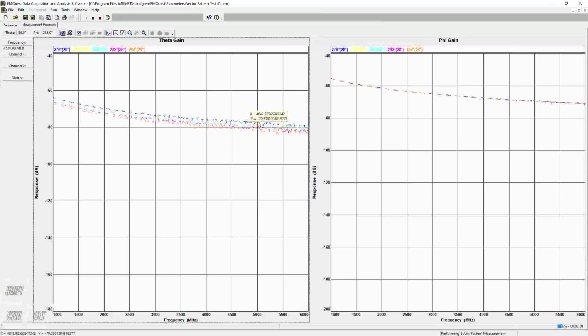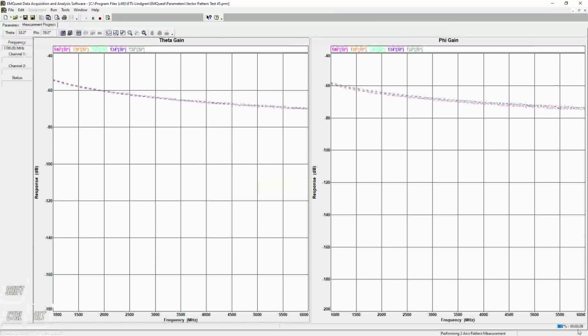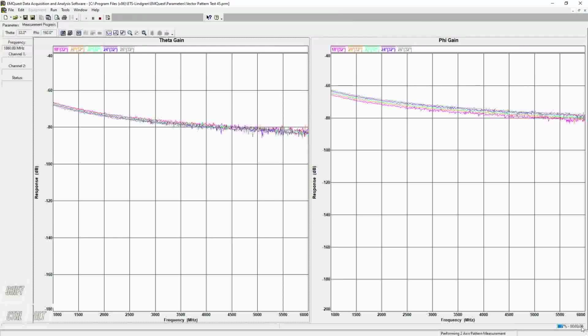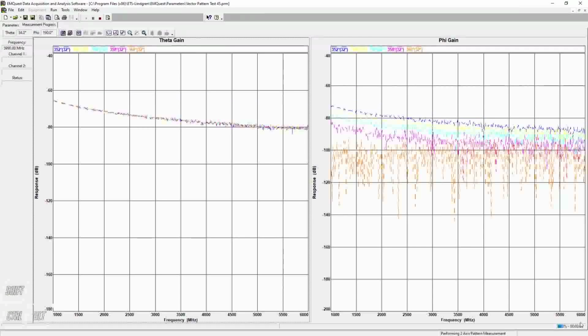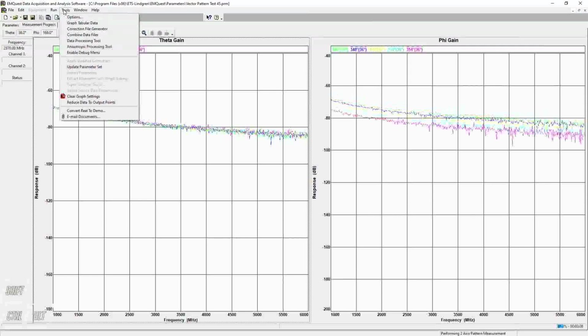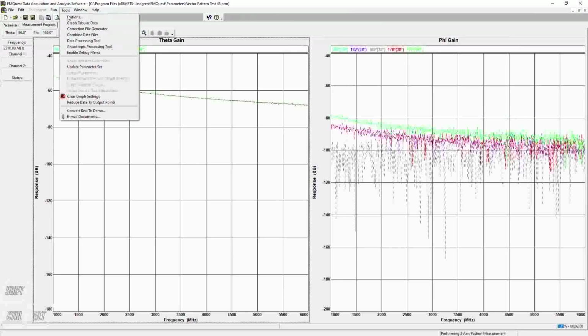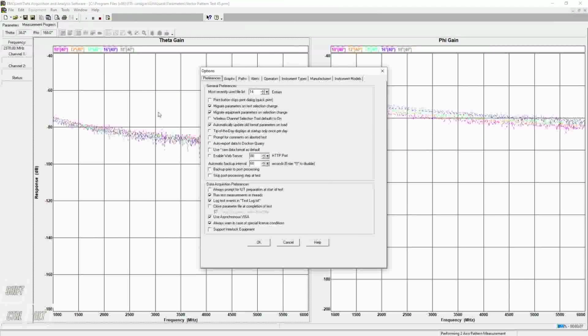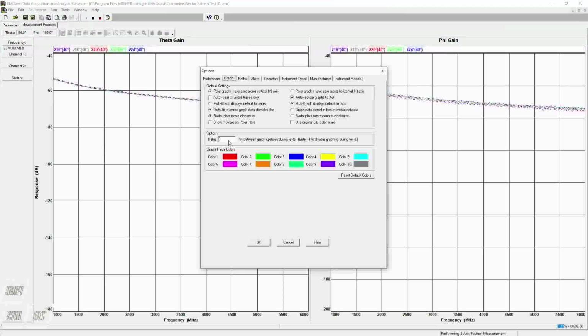The other thing I want to show, and then I'll abort this before we continue, is you'll notice that the graph is actually slowing down quite a bit. But if you watch the test timer, it's not really changing and being impacted much. Traditionally, you would have needed to come in on a test that's got this much data. You would come in and go to options, and you would actually turn off the graphing. You'd turn this to a -1 so that the graph is not trying to take all of that data and graph it constantly.